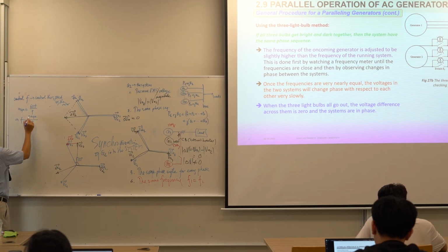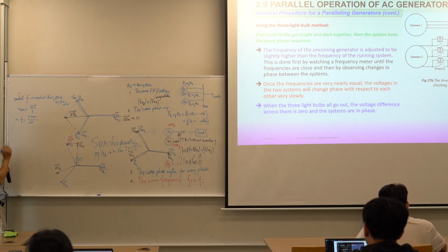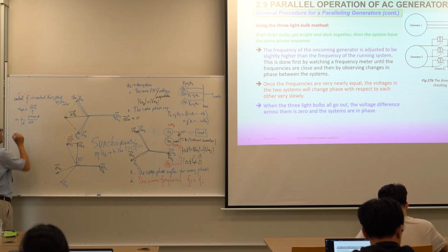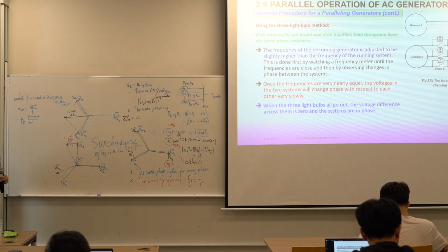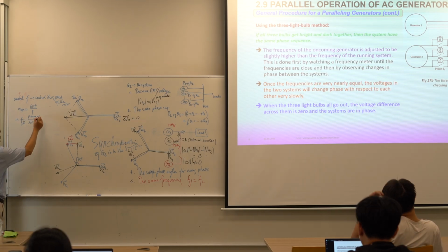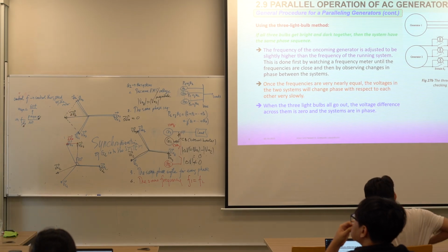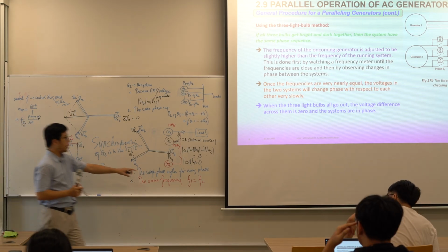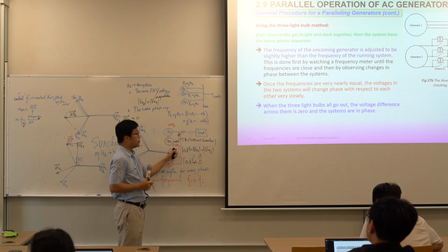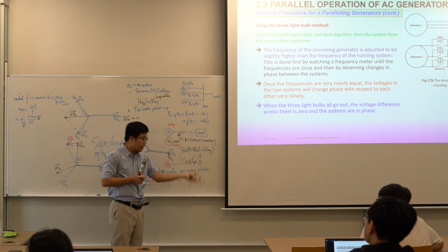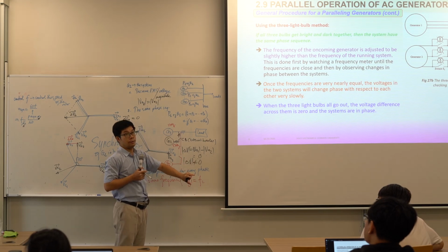The number of pole pairs is constant, and 60 is constant. So when we increase the synchronous speed, we increase the frequency. We reduce n_sync, we reduce the frequency. If you double check and recognize f_e is different from 50, increase the speed of the rotor. Otherwise, reduce the speed of the rotor.